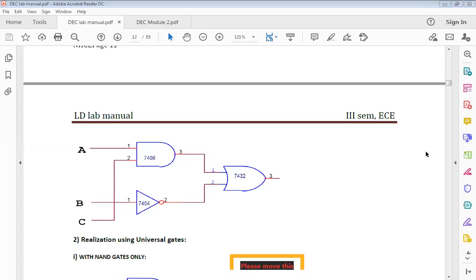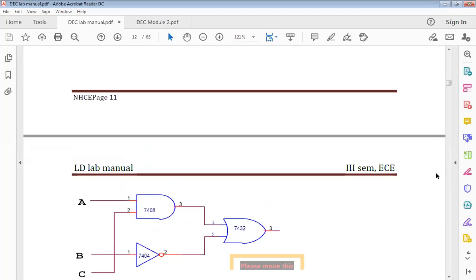So we have a basic gate, we have an equation, and then we are converting it. If it's asked to minimize, you minimize it using your K-map or using your Quine-McCluskey method, whatever method, but just follow whatever is asked in the question. Then convert them into the standard form, which means your universal gate form, NAND and NOR implementation. What I want you to do is look into the video.